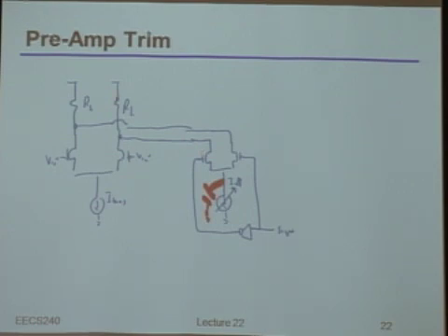Well, just like these devices, if we make the RO of these offset cancellation devices high in comparison to these load resistors, well, first of all, from a DC gain standpoint, it won't load you too heavily. But more importantly, from an asymmetry standpoint, if these ROs are all big, and your impedance is really dominated by that load resistance in the first place, the circuit still looks pretty symmetric, at least from an impedance standpoint.